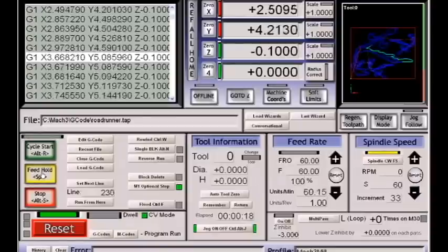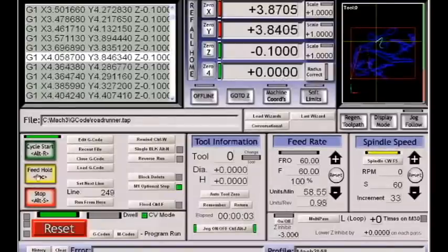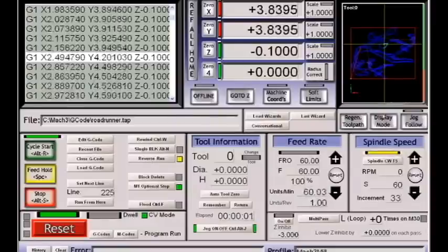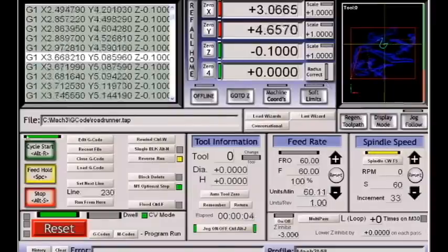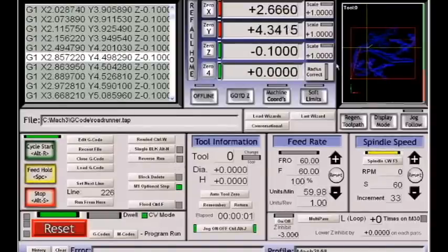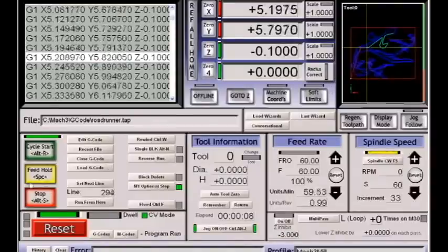We have a feed hold button, which, as you can see, stopped the movement, showed us what the next line is, and from there we can hit cycle start and continue. Or once feed held, we could, for example, hit reverse, and the program begins to run backwards. Hitting feed hold will turn off the reverse mode. Hitting cycle start will go forward again. Reverse is handy for plasma people. It's not real handy for mill, although it is used by some.